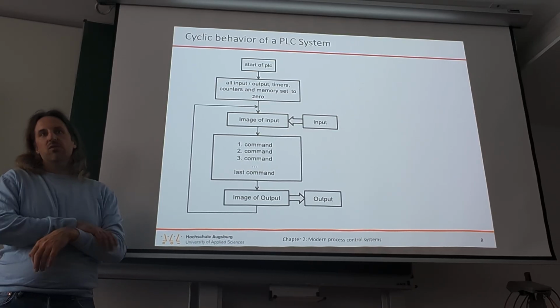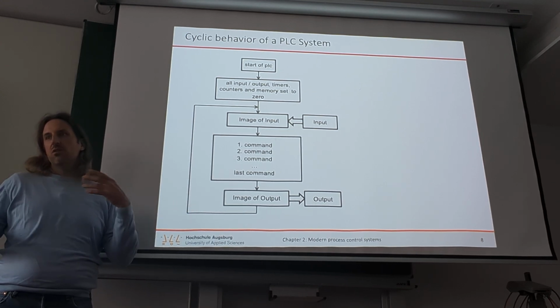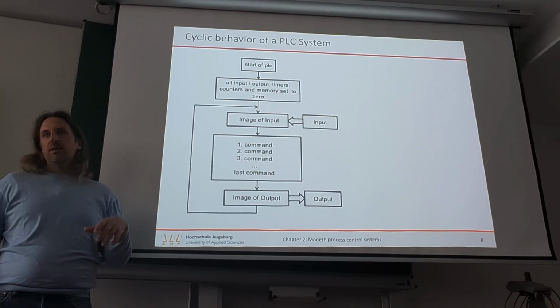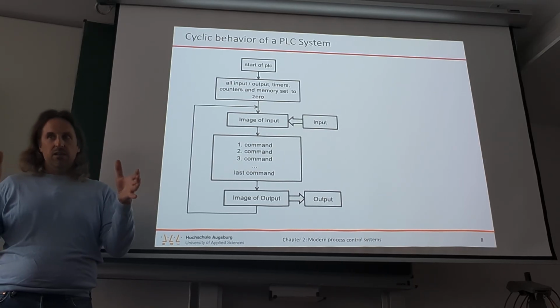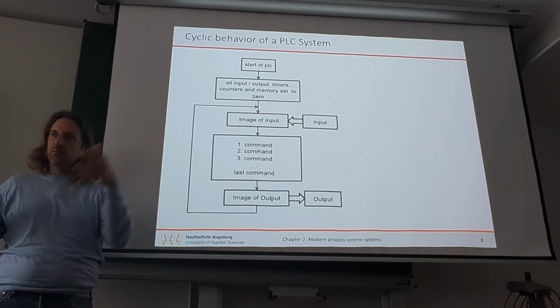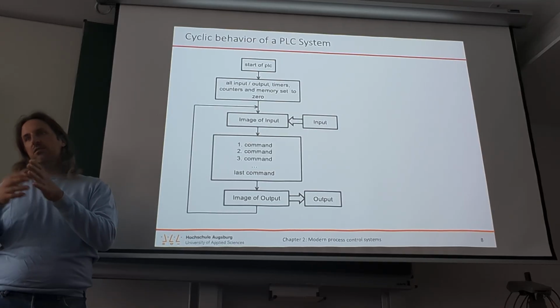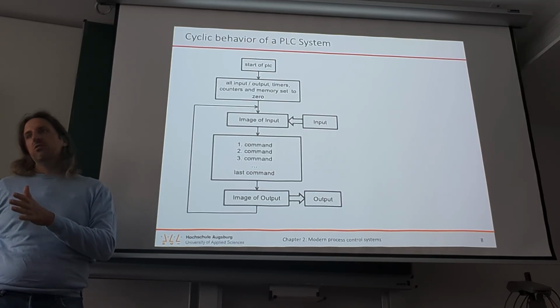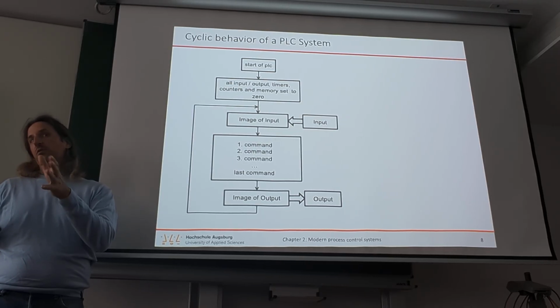That's, for example, also the reason why, if you write to a database which is not real-time capable, you basically have to write information to a buffer, and then you can ensure that you can fill the buffer within a certain time, and that's possible within a cycle. And then there must be another task that moves that buffer information to the non-real-time database. And in the end, it just has to be fast enough before the buffer overflows.